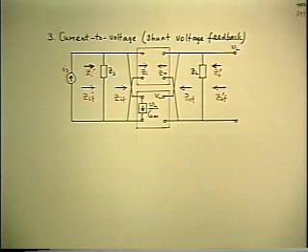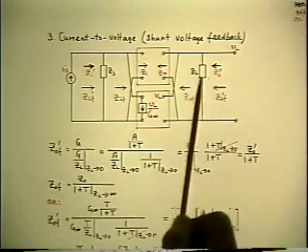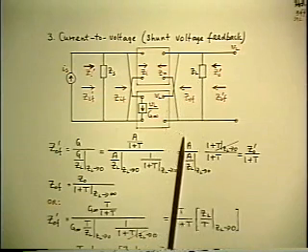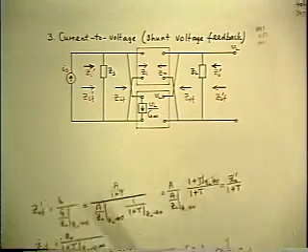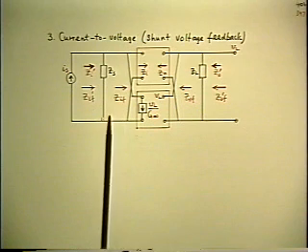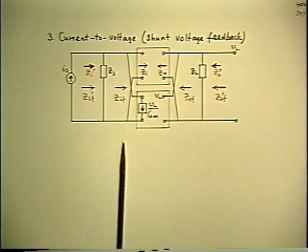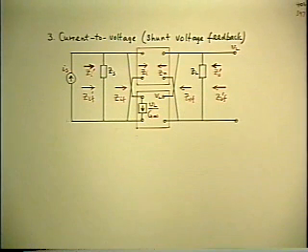And again, if I can find it, I can use exactly the same overlay. So there's the first one we have. Voltage feedback lowers output impedances. Okay, now what about input impedances? Now, once again, the input impedance formula was derived on the assumption that the input signal was a voltage, and now it's a current, so we need a new formula.